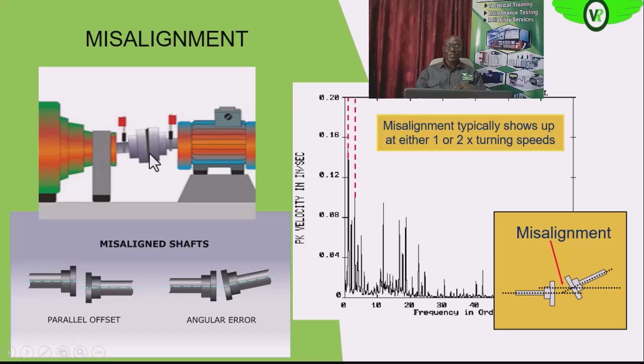Are we getting it? So this kind of misalignment, if it is in the system, in addition to the load, the motor will need to overcome that misalignment force around that coupling. So that misalignment force and the load that we are driving will mean that we will need more from the electric motor system, which means that we will be overloading.